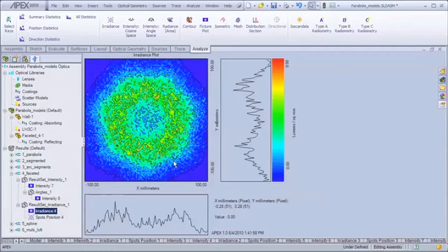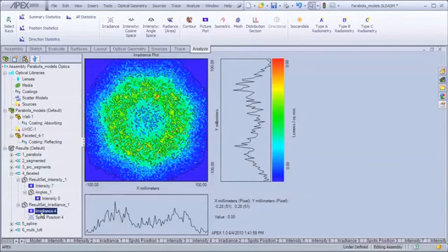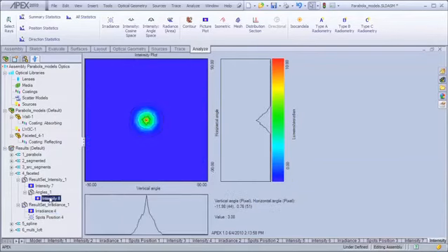So this has been a significant improvement upon any of the previous designs, although obviously we could make it a little bit better still. But we also have to remember that I have the detector surface at one fixed location, and typically what we want to be able to do is to illuminate over a wide range of distances, which means we need to have a narrow angular spread. And in this particular case, what we see is, yes, we're getting a good energy distribution, but at the cost of having a somewhat wider spread of energy, although in this particular case, most of the energy is within, say, a 10-degree bundle, based on the information we see down here. So again, there are always going to be trade-offs in any illumination design, and sometimes to get a better irradiance pattern, it is at the expense of the angular spread of the light.